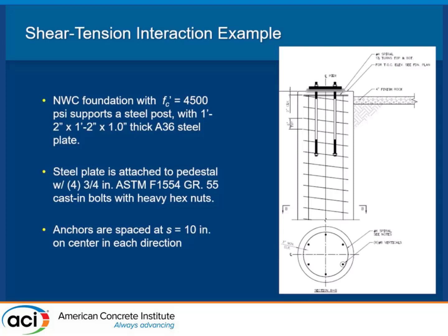making the calc? I know if I'm this far deep and I know I have to go this far deep, or if I'm maybe further up here and I would just go a little further down, why don't I just use this as anchorage reinforcement? It's just sitting there waiting. Why even do the check, right? But you can do the check, but remember your H effective is going to climb way up here, and so all your calcs are going to be off as if that headed anchor was here.